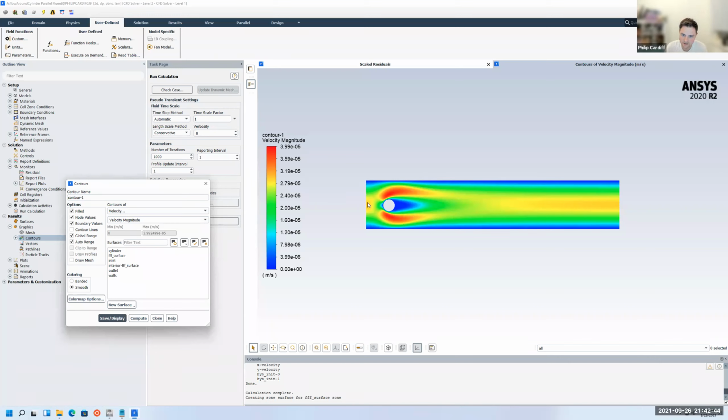The inlet velocity profile here, you can see it's highest in the center, lowest on the outside. So that is our parabolic inlet profile. If you're writing your own UDF, you should really double check or verify that what you think you coded in is what you intended to code in. So you might plot the line along here and just check those values are the same as what you created in Excel, for example. So you can see the average should be 2/3 of the peak, and the peak here should be 4. So it's almost exactly 4. If the mesh was finer, we would get one cell with 4. So that's the parabola. The average is like half the peak.